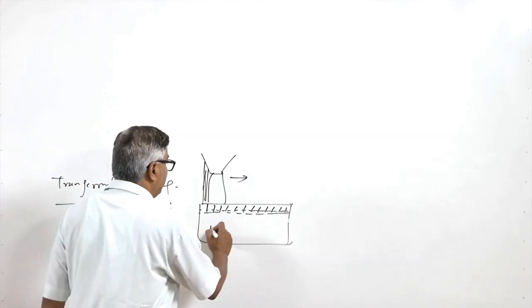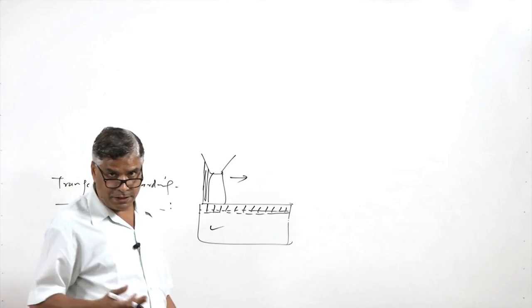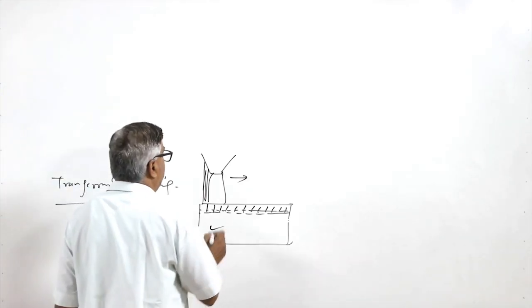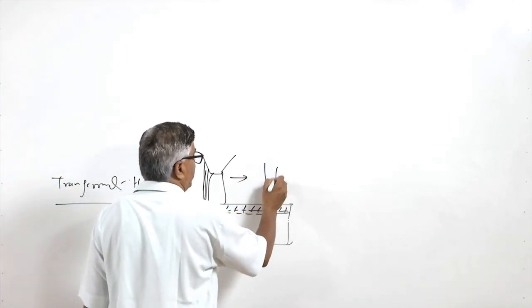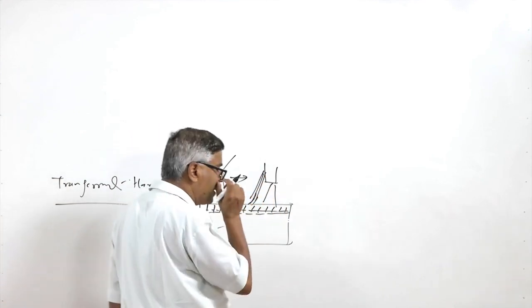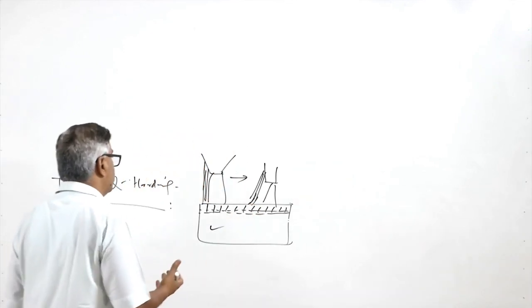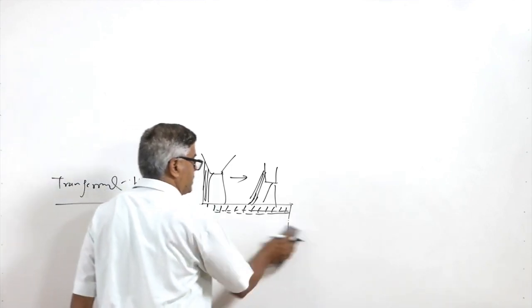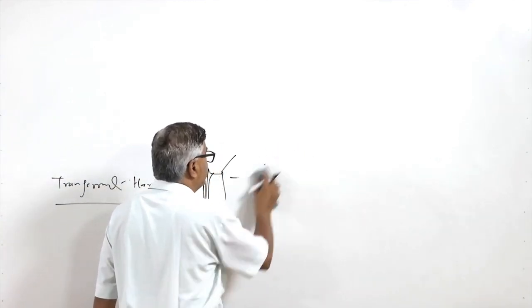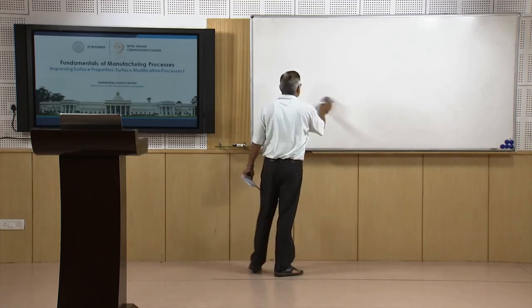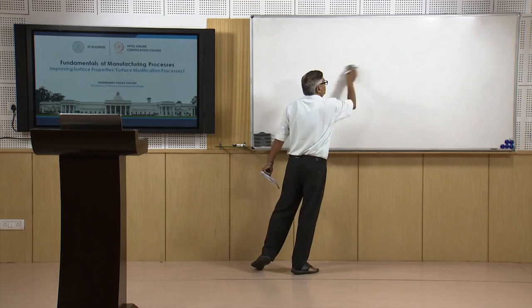So, automatically the base metal will not be able to provide sufficient cooling rates to ensure that the austenite to martensite transformation takes place, and therefore we need external cooling. For that, once the heat source has passed, we apply a jet of water so that the zone which has been heated to the austenitic state can be quenched in order to have the suitable martensitic transformation.